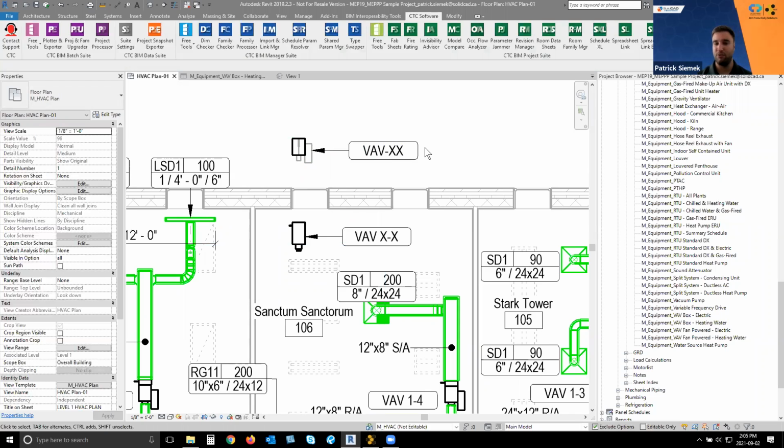So again, looking at the cycle with Hive, we started initially with the Parameter Jammer. A Revit end user wants a family to work within the project and needs to get it working with the schedule. They download the family, load it in, and use the Parameter Jammer to force specific parameters to work and to be updated within the project itself. In the BIM manager role, the families that end users are using within the projects have to be modified with additional shared parameters, additional formulas, and any additional information added to the family itself. That's where our Family Processor was used, to round trip all of that.